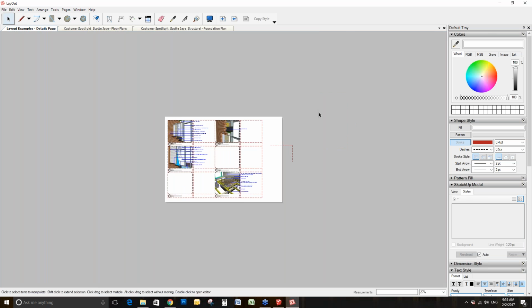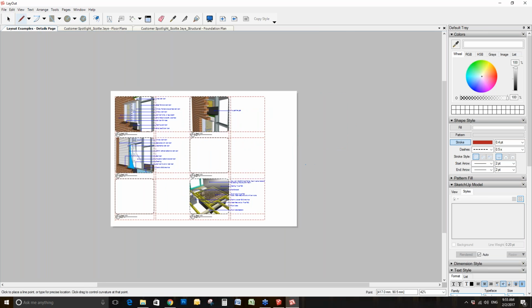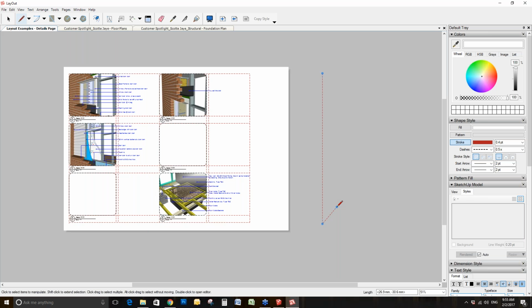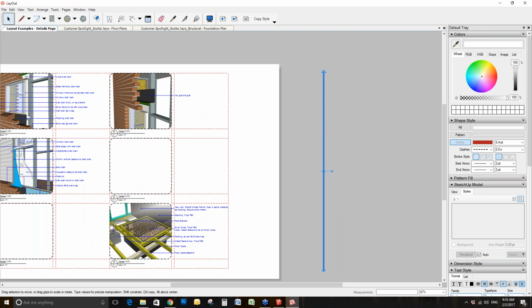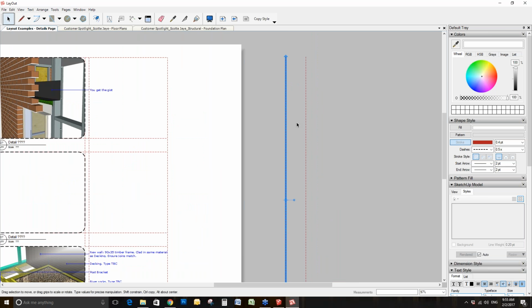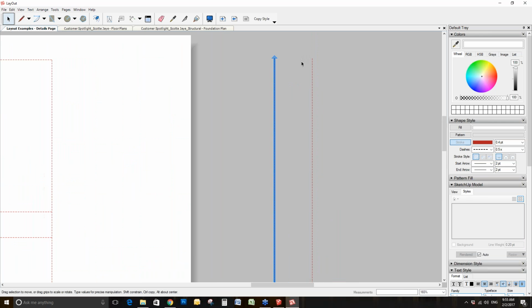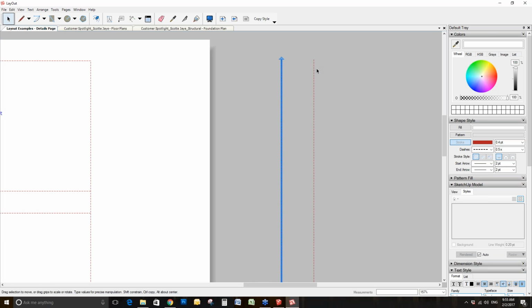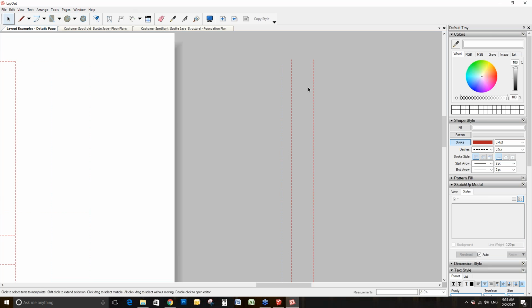To set up the grids, all I did was space them. I just went, okay, I know that this is the extent of the drawing that I want, depending on the paper size that you're using. Also, in layout, you can copy and move things and draft them purely using layout to scale. The only difference is you can't draw 1:1. You have to know the scale that you want it to be in. So if you're drawing it 1:100, after you've moved it, you're then going to type in the distance that you actually want it to be to read at 1:1.